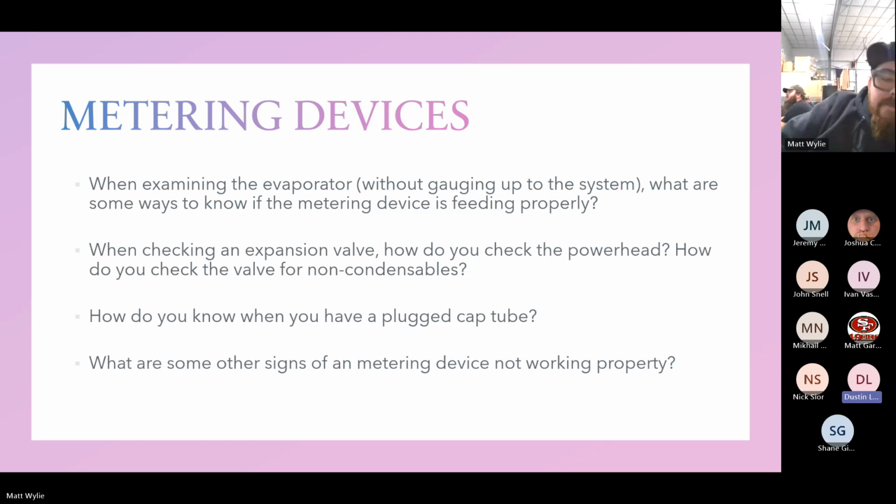While we're on the topic of expansion valves, we run into a lot of older stuff. Does everyone on the call know that if you ever don't know what your gas type is, a good place to start is to check your expansion valve and see if it's got the little clip on it that tells you? Sometimes, like the manufacturer-specific ones, the valve itself will indicate a refrigerant, and the power head indicates a refrigerant. So if you're ever not 100% sure, you can always go to your valve and see what it's rated for as well.